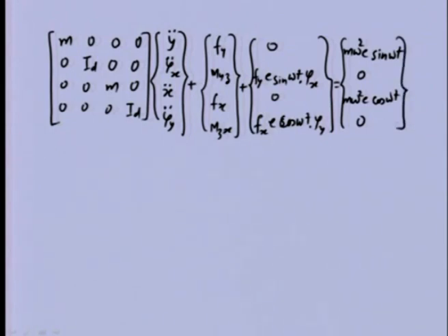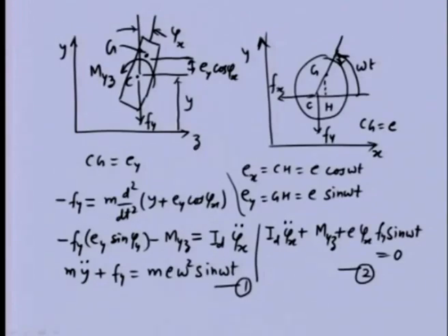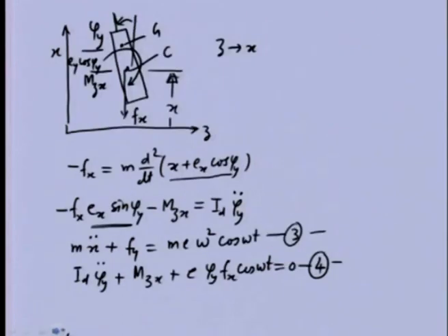I have written those four equations of motion. So if we again see, this is the first equation. This term will give the mass matrix, which we have tagged separately, and this is the unbalanced force. Similarly, we have the moment equation; there was no external moment, so that term was 0. So these two equations, and then the third and fourth equations, I have kept in matrix form.